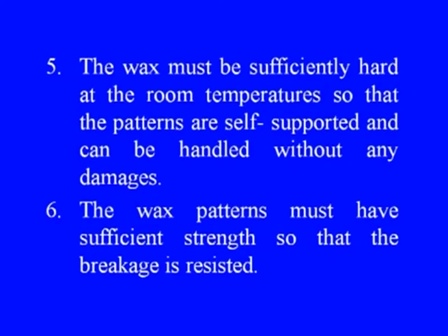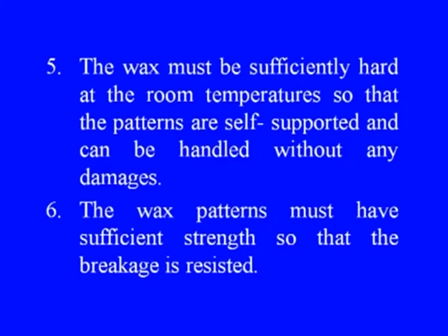Number 5, the wax must be sufficiently hard at the room temperature, so that the patterns are self supported and can be handled without any damages. This is another important aspect. Handling also should be easier. Otherwise, the cost incurred in handling will be much more. Number 6, the wax patterns must have sufficient strength so that the breakage is resisted. This is another mechanical consideration as far as the pattern is concerned.